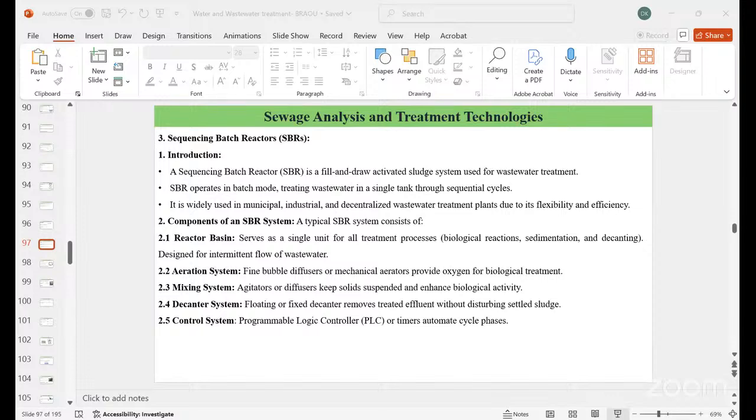So coming to the next one, which is chlorine dioxide. This is another strong oxidant that disrupts the microbial cell membrane. It is effective against a wide range of pathogens, does not form THMs, and is also effective over a wide pH range. The disadvantages are that it must be generated on site due to its instability, and it can form chlorite and chlorate byproducts, which are again not healthy.